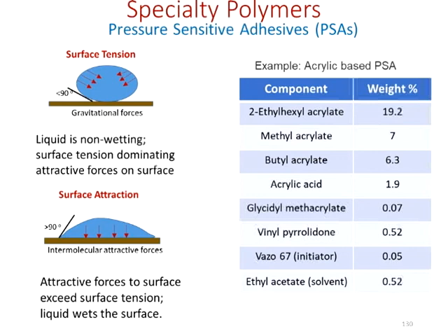And then we have the solvent. And so you make this blended material and then you cure it out. You notice it's a very low solvent blend of material, and that's kind of good because it helps the environment. We show you what non-wetting looks like in the top diagram. The angle there is greater than 90 degrees. So when it's greater than 90 degrees, it won't wet. When it's less than 90 degrees, it will wet. And so that's what this is intended to show here.